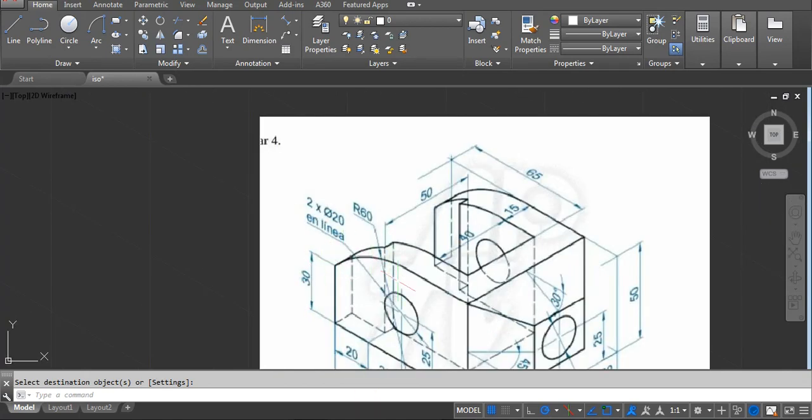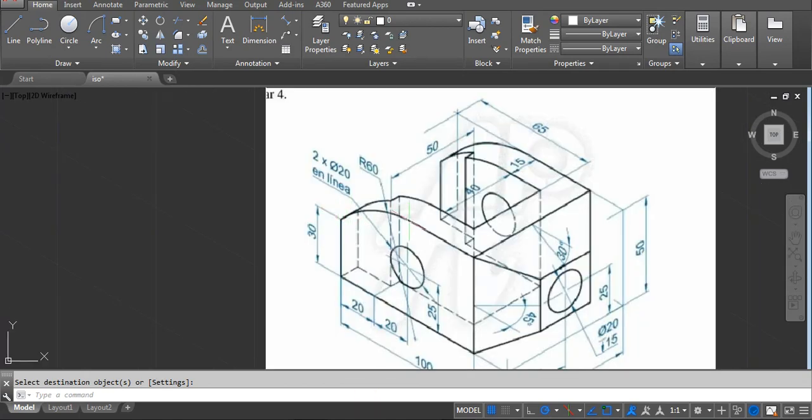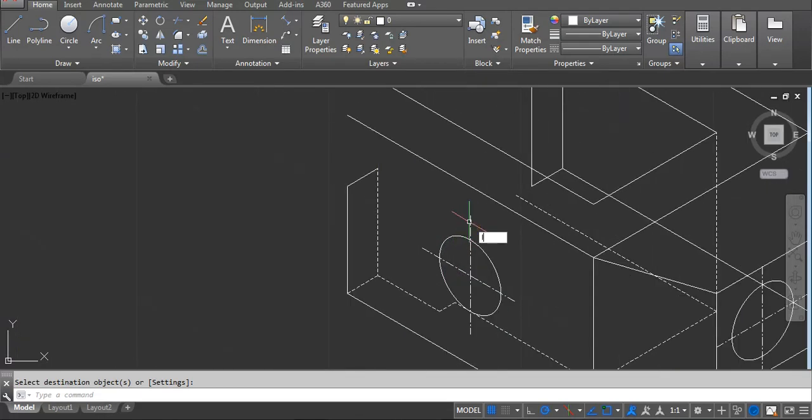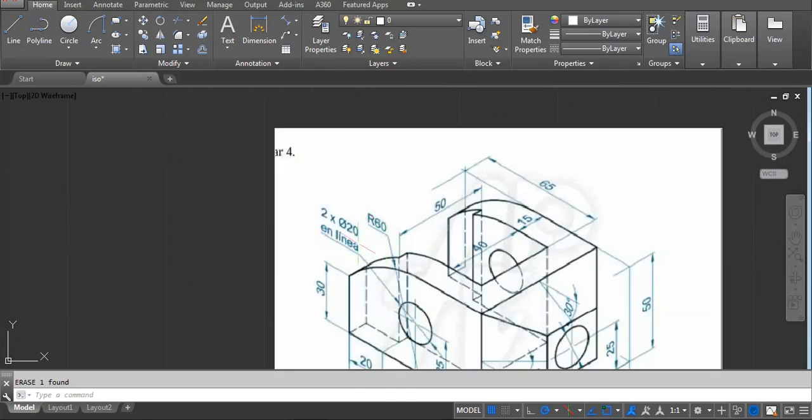So this arc comes, you can see here to here, it comes from the 40. Clear? This portion. So you can take a reference line like this. Now you can see we have a starting point, we have an end point. Clear? Let me trim this line so that you will get more clear. You have a starting point and then you have an end point, and then radius is 60.